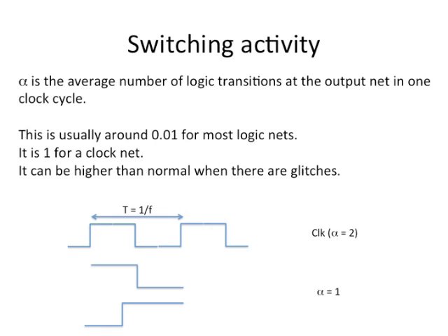These usually happen due to the signals coming into the gate. So there is a logic gate which is driving the net, and we are looking at the number of transitions in the net. If the inputs are coming into that logic gate with different delays, then in a clock cycle it might happen that the input pattern is such that the output goes to 1, then the input pattern changes because things are still stabilizing. It could go down to 0, then it could become 1 and 0 and so on.